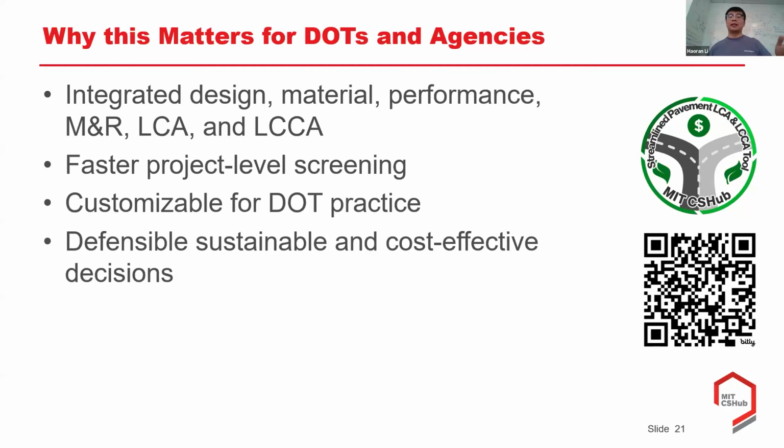And we can see that we are not only considering the LCA, but also LCCA, and you can see the LCA and LCCA are so comparable. You can see the difference whether you're only interested in the embodied emissions and agency cost, or you're also interested in the trade-off and payback time, how long you have to wait for one pavement alternative to perform better than the other. What about the cost perspective? Sustainable pavement has a lot of things that come with it to help make better decisions. And also you can see we involve the statistical analysis to give you a sense of the confidence levels of your results.